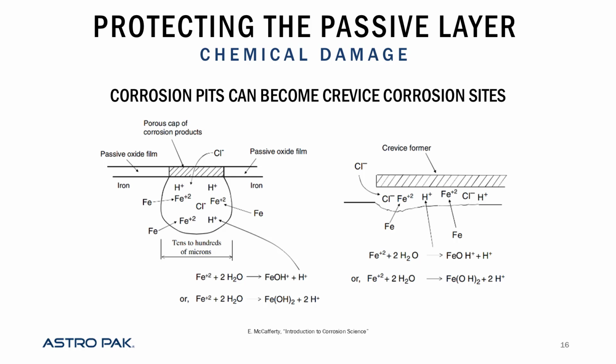So maybe 100 ppm of chloride will work for you. It's probably going to be less for hypochlorite. So understanding what source of chlorine you have will help in understanding the corrosivity of your environment. Here's a snapshot from a textbook I love. I cannot go 2 weeks without opening this PDF on pitting. So that shows where I'm at.